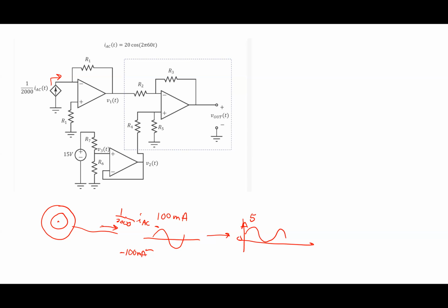Right? So what am I doing? A microcontroller has what's called an analog to digital converter. It takes this analog signal, which is continuous, and converts it to digital. You haven't learned that yet, but basically if you've used a microcontroller, they have a voltage range, maybe on the order of 0 to 5 volts. So I got to take that 100 milliamp waveform and get that into a voltage that goes from 0 volts to 5 volts. That's what's called signal conditioning. If I'm doing an embedded system, I would have this type of thing to shift those voltages around. Okay.